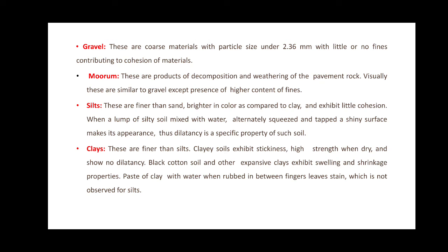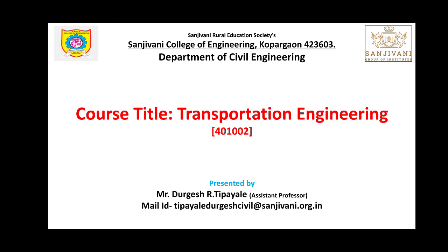Here it should be noted that clay is a type of material which will cause deformity to the pavements, as it can swell and shrink under the climatic conditions. So greater care should be taken by the engineers while designing the pavement regarding the presence of expansive soils beneath the subgrade of the pavement, and necessary corrective actions must be taken. With this, we shall stop here. Thank you.